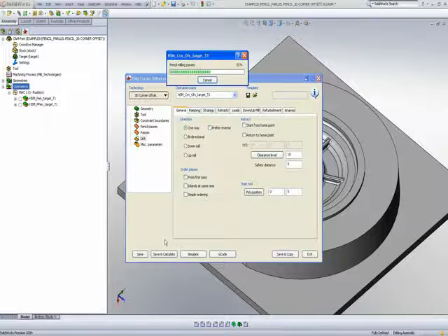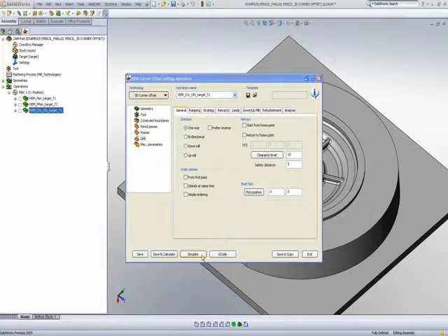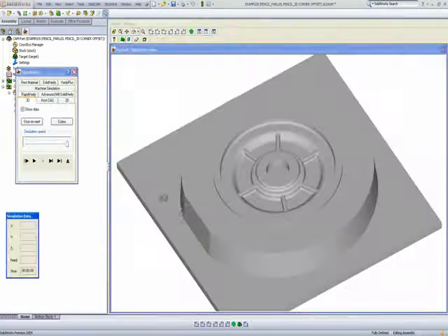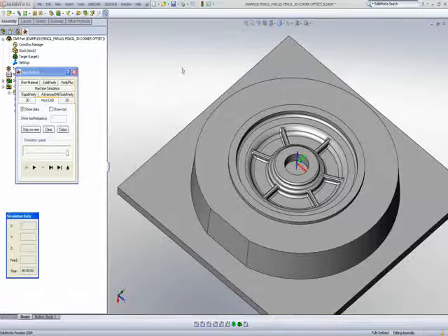Now let's take a look exactly what happens. In my simulation, you'll note that it'll work in every single one of those areas, and the boundaries that it'll be working with will be the pencil milling boundaries that it picked up, and it'll work in those areas using the option of 3D constant step over, boundaries picked up automatically from the pencil machining. Now if we actually look at the simulation itself, this time we'll use the host CAD simulation.